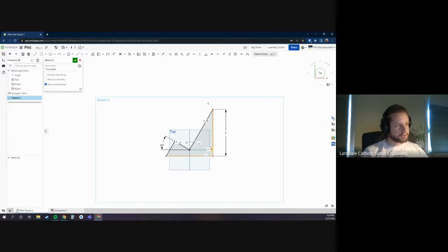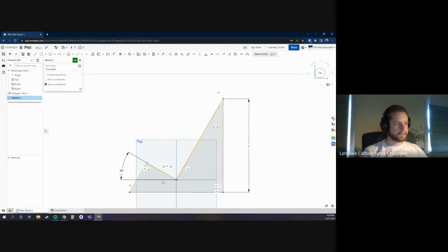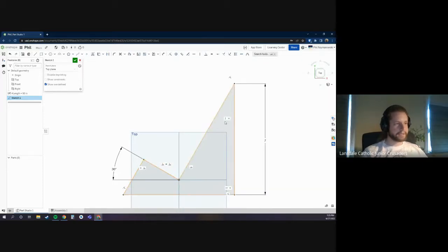And also note that when you mouse over a constraint, it highlights the two things that are constrained. So like this equals, it shows you that those two lines, those two yellow lines now, are the constrained lines. And the same thing with the perpendicular, and this perpendicular, and this coincident, showing you those two lines, the endpoints of those two lines are coincident. So there's a lot of visual highlighting that Onshape does that helps you understand what your constraints are doing and where they're coming from.